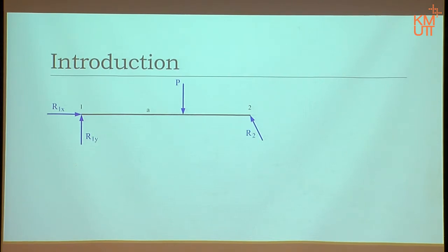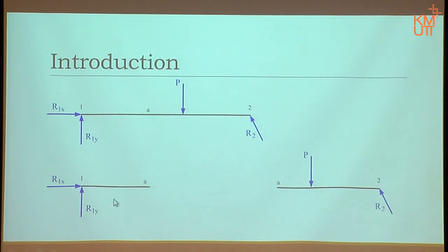Let's look at point A, just a point on the beam, and see what happens. Now if I want to see the force at point A, what do we do? We go back to the concept of the free body diagram as usual. We just separate them out. Then I can separate this into two free body diagrams. If we look at this picture, that is the body, and these are the environment.